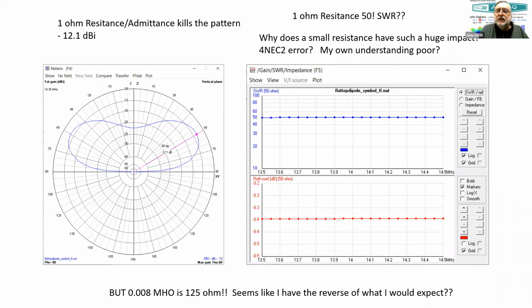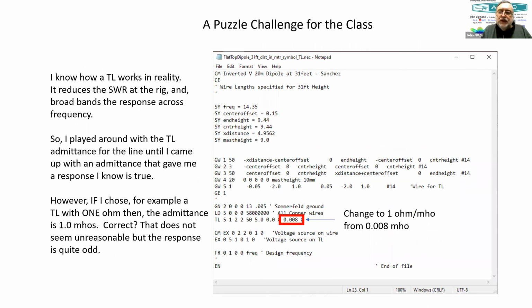So what you're seeing is primarily the load with some parasitic thing, which is an antenna with a transmission line on it that's just contributing a little bit of noise to the situation. So a 1 ohm shunt across your feed is going to give you a 50 to 1 SWR. So no surprise here.